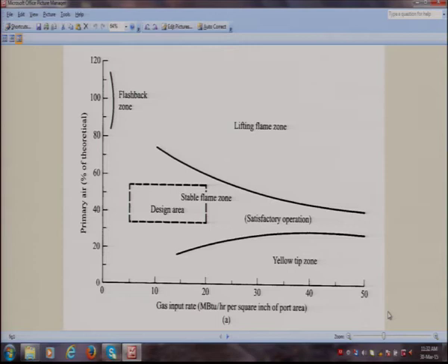Okay. And this particular burner, I do not have the details of this particular burner. This is some burner for which a stability diagram is available. It is included in Turns's book, and that is why we are looking at the stability diagram. I do not have full details of the burner itself, but it may not be a simple tube, and in any case we are not doing 100% premixed flame, in the sense that 100% premixed would have been if you are sending all the air that is required for combustion along with the fuel. So, if you look at the stability diagram, you understand that that is not exactly what we are doing.